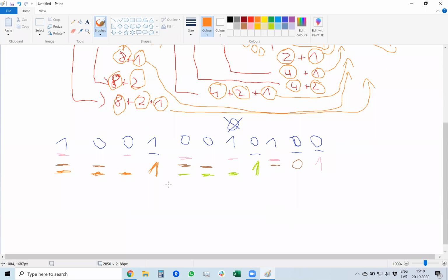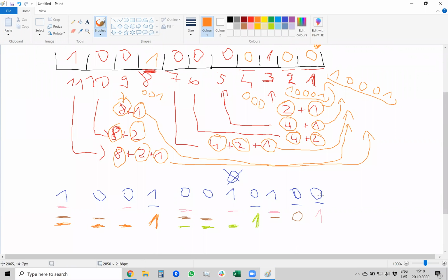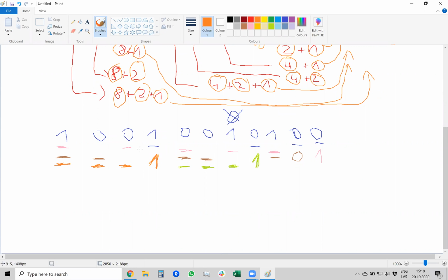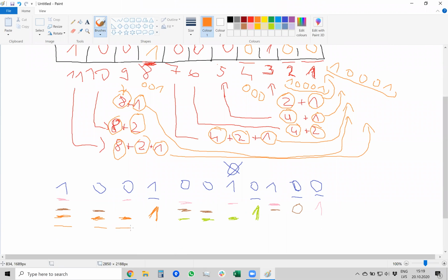So I guess I have to do XOR on the parity bits that I received and the parity bits that I calculated. So this parity bit is the same. So basically we know that the mistake is not in locations number 11, 10, and 9, because parity bit number 8, which is calculated on these three numbers, is the same as the one that we received.